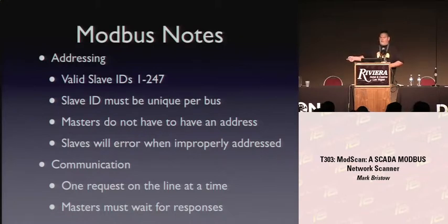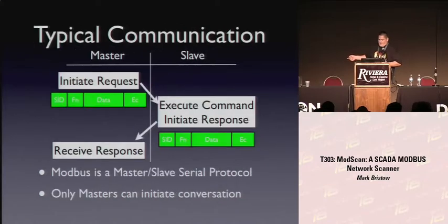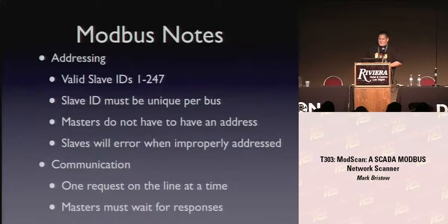Masters, if you look back in that slide, the masters don't announce themselves in any way. They just send something on the wire. See, there's no master ID in this packet. There's just slave ID. So masters don't have to authenticate in any fashion. And you can only run 1 request at a time. It's really, really highly timing based. The good news is that straight Modbus is not really run a whole lot. I've seen it in some systems, but it's not everywhere. But if someone's running just straight Modbus, you can do really nasty things to them pretty easy. It's pretty bad.